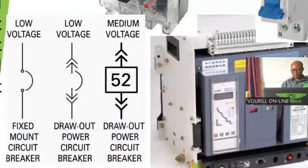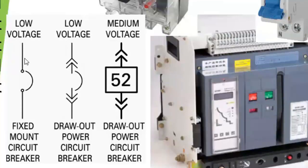As you can see on your screen now, these are the symbols of the circuit breaker and how they are represented in electrical diagrams. This one depicts fixed mount circuit breakers, those breakers that are permanently installed in the circuit or in the cabinet. Then you see the symbol of the circuit breaker followed by a double arrow up and down. These double arrows tell us clearly that this is a detachable circuit breaker, or a draw out circuit breaker that you can actually rack out of the circuit.